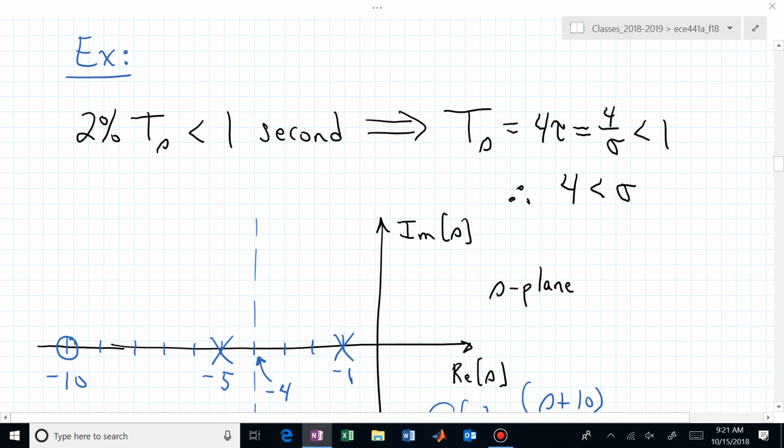Now what are the dominant poles? They're the ones that are the closest to the origin. So you start drawing targets or overlapping circles, and you're looking for the smallest circle that contains the first 2 poles. Those are your dominant poles. In our case, let's say that we want a settling time less than 1 second. We can now translate